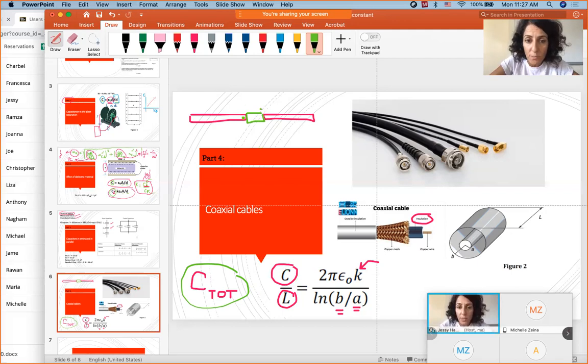By the way, you need to subtract the capacitance of your adapter, and for you to be able to do so, you measure with the adapter and without the adapter, so you can tell the capacitance of your adapter. I'm going to give you all the measurements and you do the work, okay? Let me now move to the videos. I think we're ready for the videos.